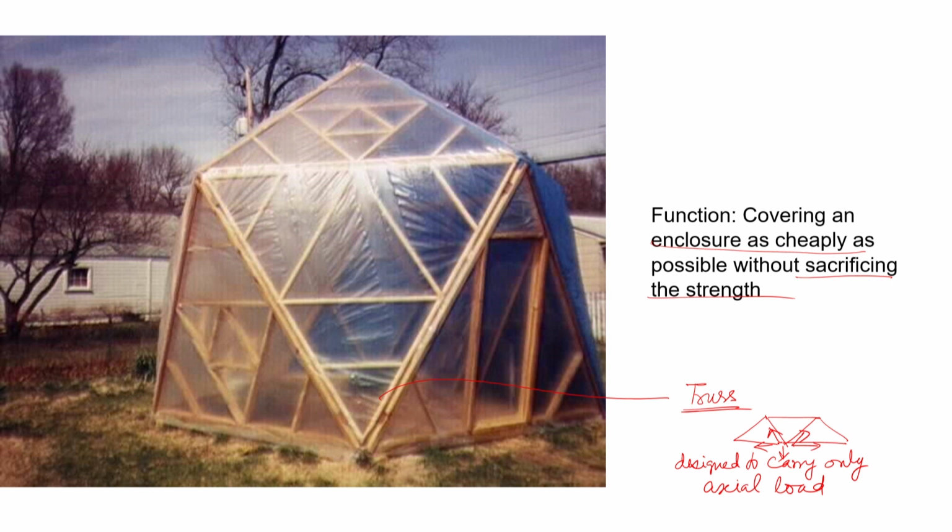The joints are all pin joints, they would not allow any moment to be carried. So, that is the way the trusses work, and then the trusses again are of different types like determinate or indeterminate structures, etc., that I am not going into the details, but again this particular type of structure has been chosen keeping this functionality in mind.